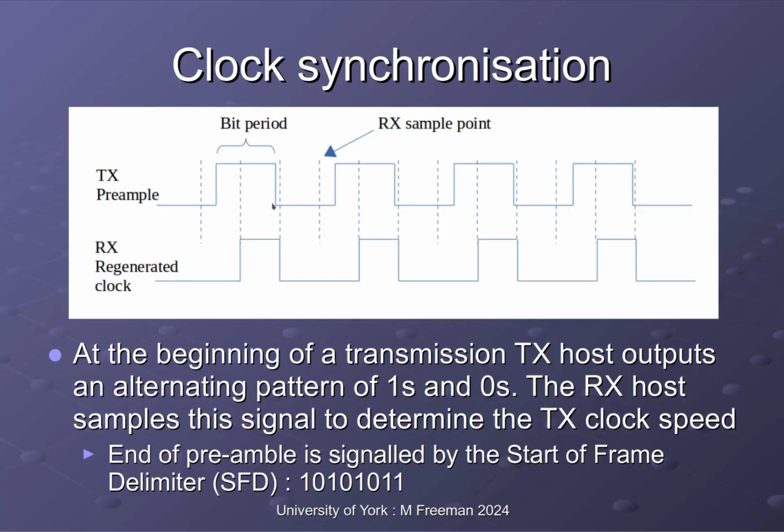So this is the period of our incoming signal. So this will be obviously twice the clock frequency of the thing sending it, because on each clock edge we'll be changing the state of this data signal. And as it's received the other end, we need to sample that at these sampling points, obviously twice the frequency of the incoming signal.